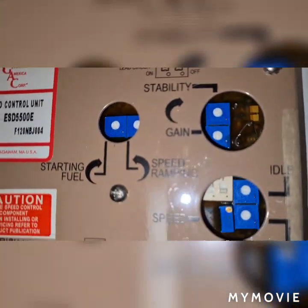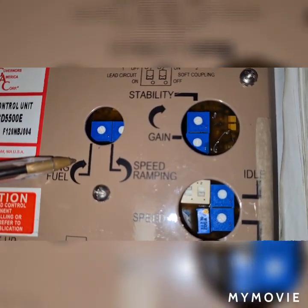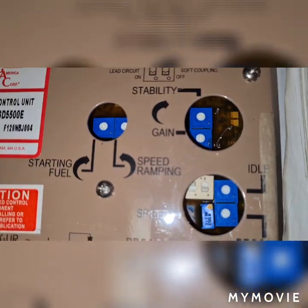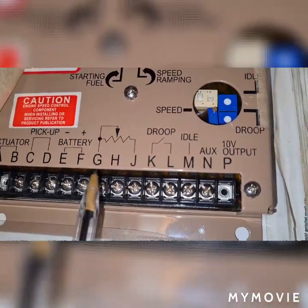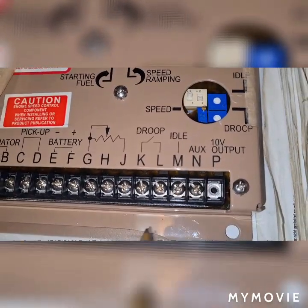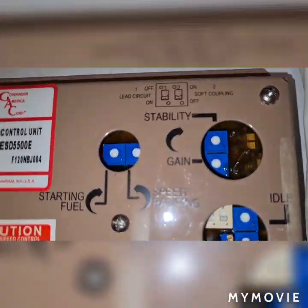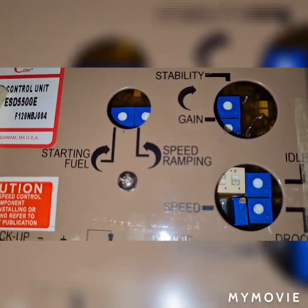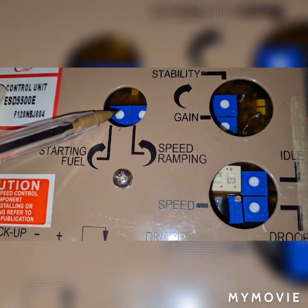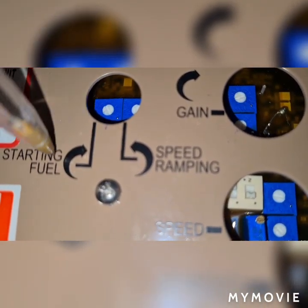So in here you have a potentiometer inside. So this is your starting fuel. What you're going to need to do is connect the terminal M, that is M, and that is G. You have to put a wire on it. So while the engine is running at idle and you see that your engine is emitting very dark smoke, you must rotate this potentiometer in a counterclockwise direction.